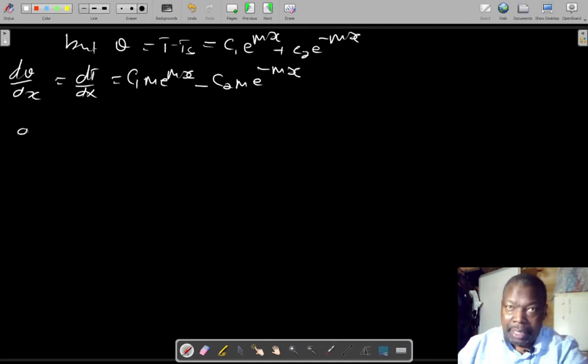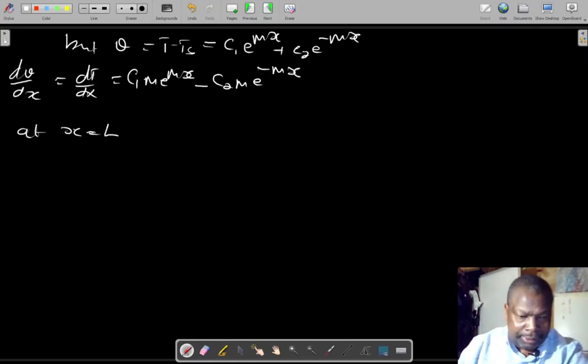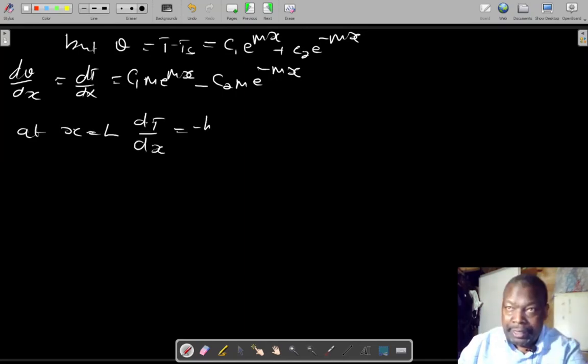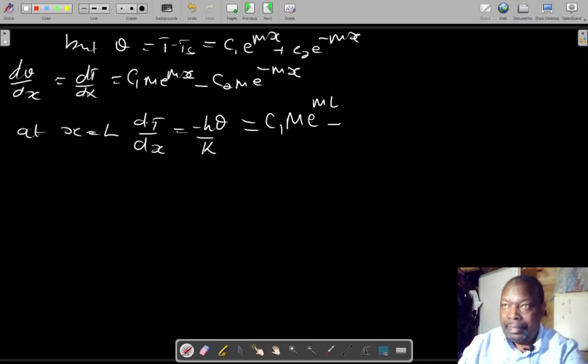Okay. At x equals L, we have dT by dx equal to minus h theta L over k, which is equal to C1 m e^(mL) minus C2 m e^(-mL).